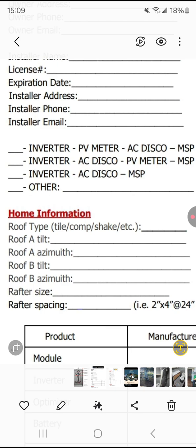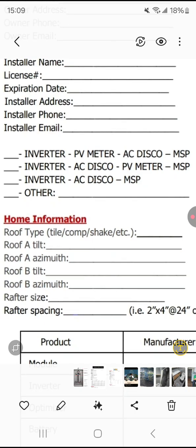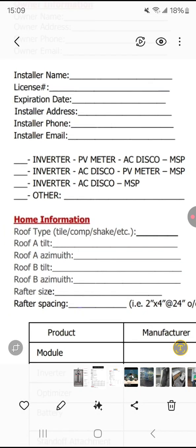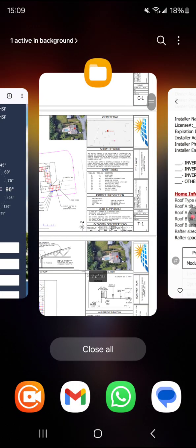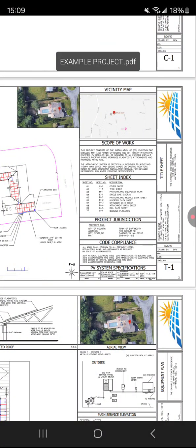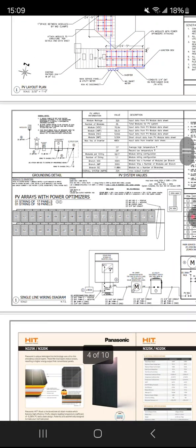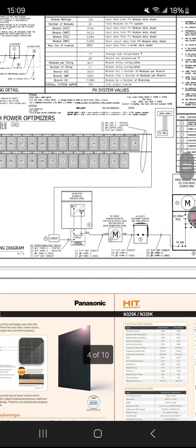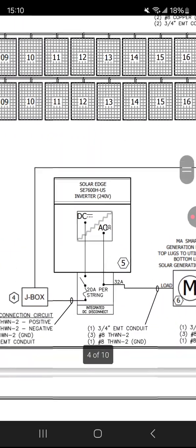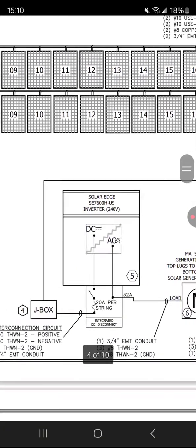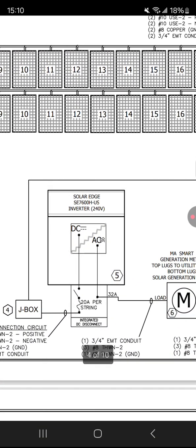The next piece of information is the stringing. There should be a headliner there called stringing, but this is, how do you want the solar project to be strung? This is going from left to right, from the rooftop all the way down through to the main service electrical panel, the MSP. Coming down from the roof, you have the solar panels, and it goes into an inverter. I'll show you on the plan set here. The solar panels are on the roof. I like to show this on the electrical page. They come down to the inverter. If you have a box type inverter, sometimes you're using microinverters that are actually on the solar panels, in which case the stringing might be different.